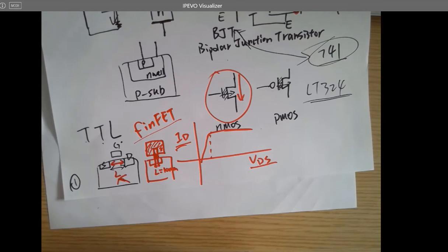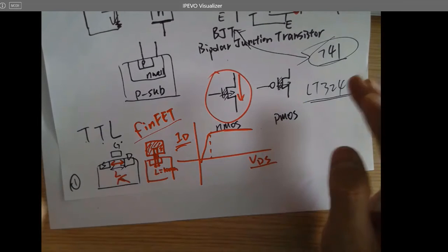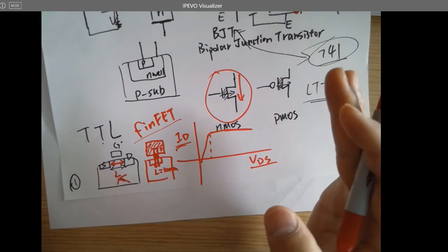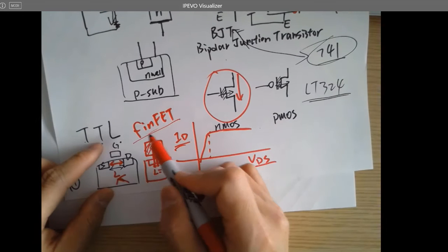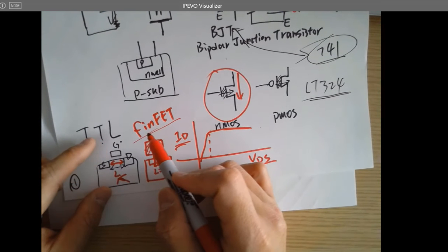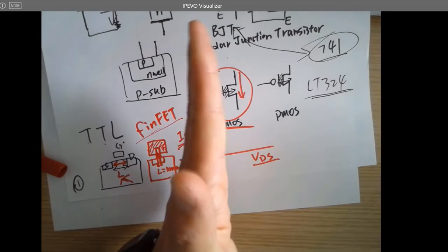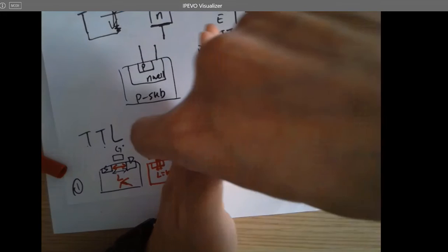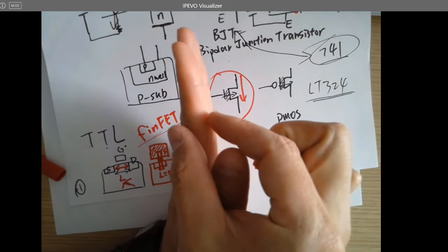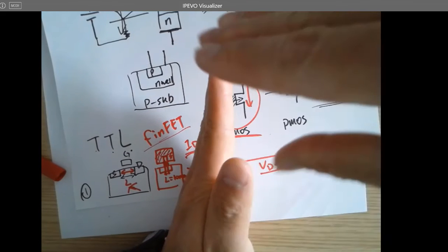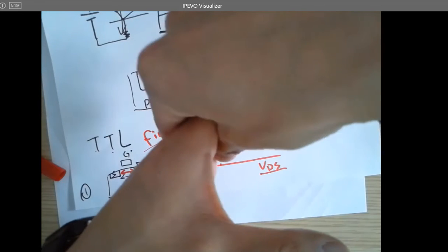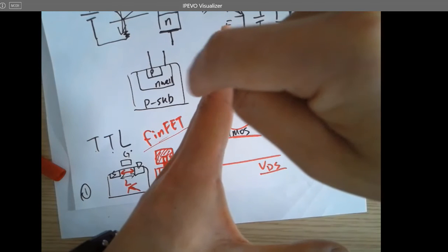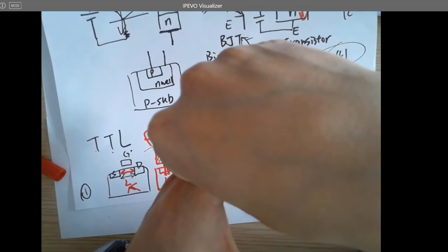So that happens starting from 7 nanometer, and then when 5 nanometer and 3 nanometer become available, they find out FinFET is still not ideal. So what's next? Here's a fin, right? Here's the length of the channel. That's the length of the channel. Here's a gate. I can give a voltage to the gate so the electrons can conduct through the length of the channel. But still not good enough for 3 nanometers.